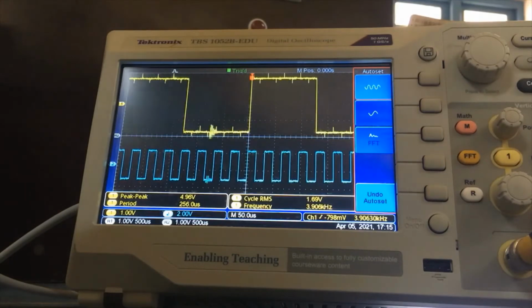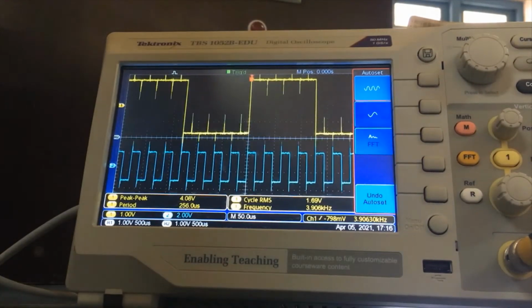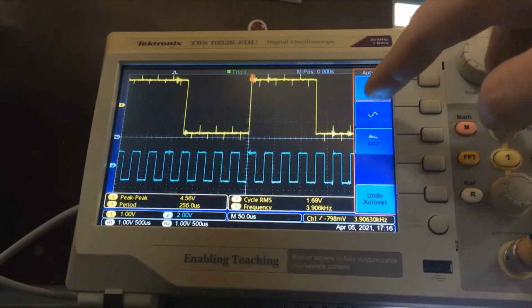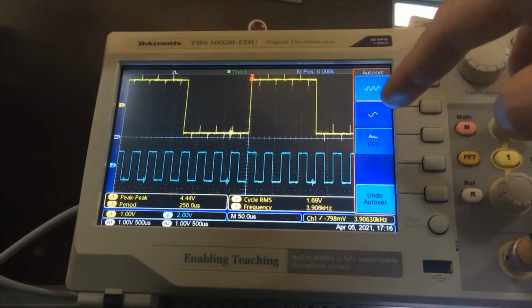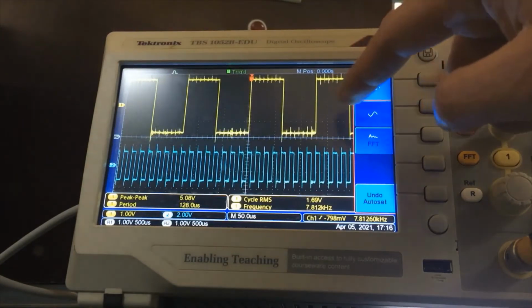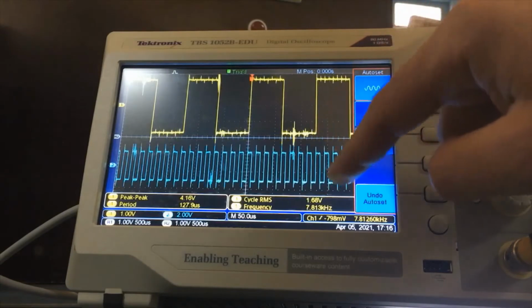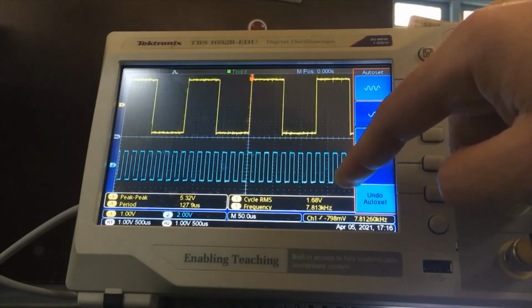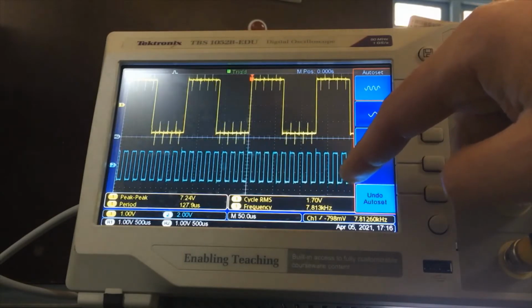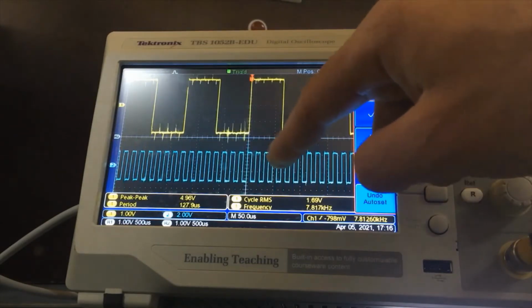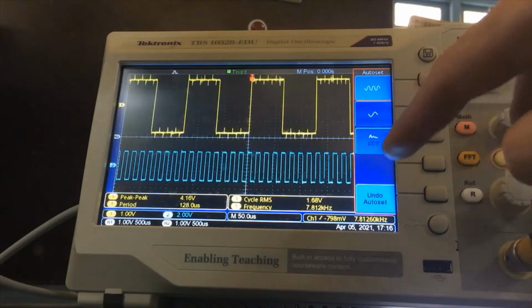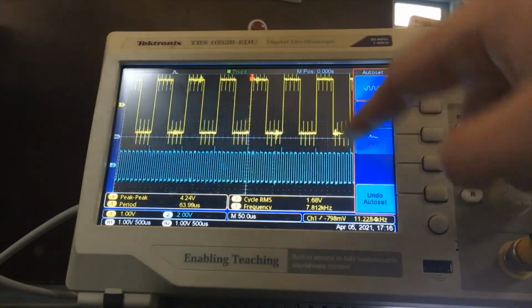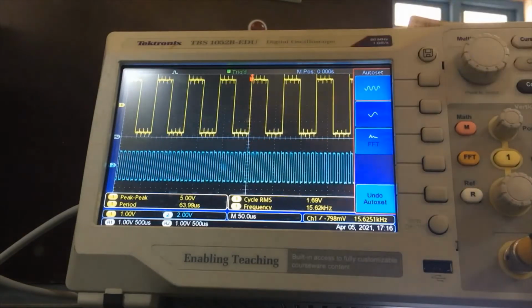Now what we can do is change the sampling frequency from 4 kilohertz to 8 kilohertz, double, right? So it is now doubled. Over here you can see the clock of the parallel to serial converter also increases, the frequency also increases 8 times, and you can increase the sampling period. This is 16 kilohertz, and it changes correspondingly.